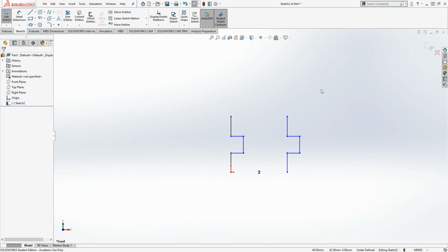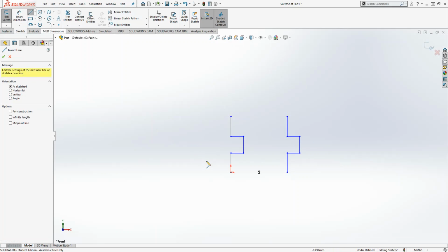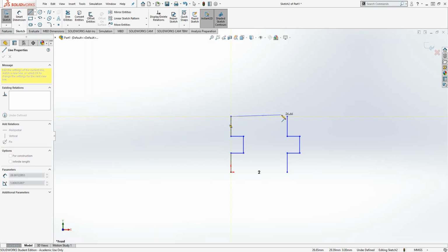So I've got it about 3 centimeters or 30 millimeters in one direction. I've got the pattern. It looks pretty good overall. So as you can see, I have direction in the X direction, a distance, the spacing, so I could create even more versions of this sketch pattern.